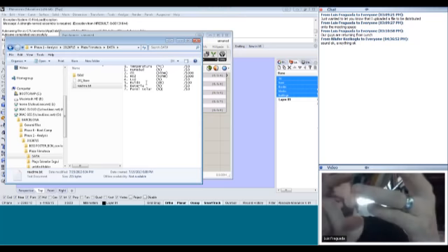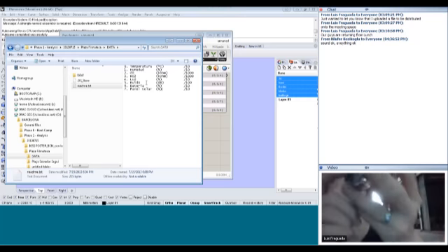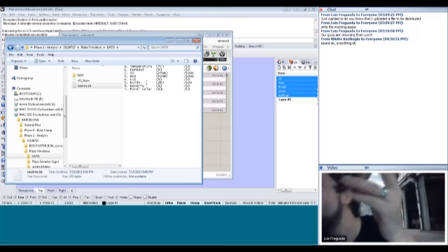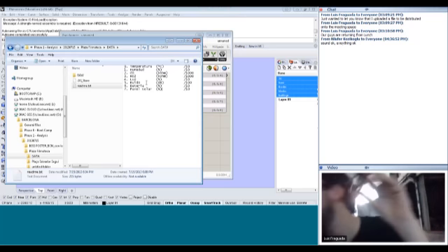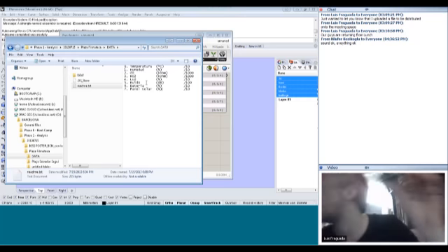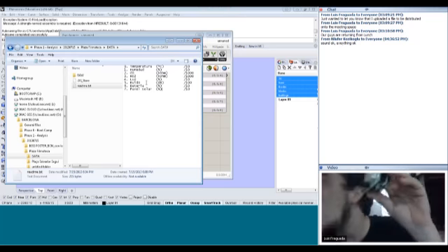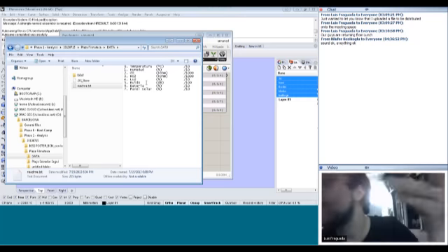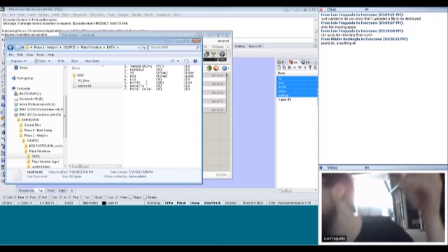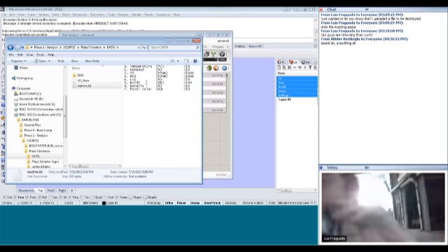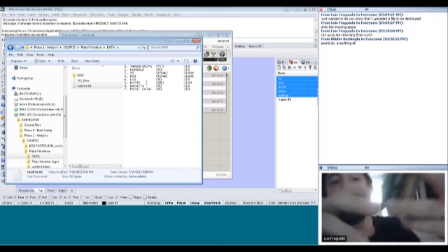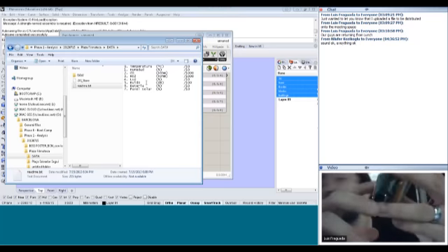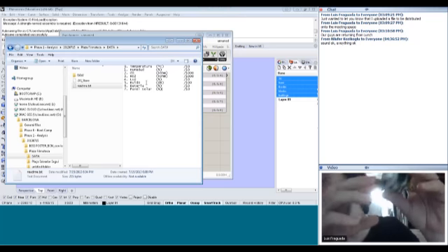So this temperature sensor has a specific behavior, that at a certain resistance equals a certain temperature. At a certain resistance, it equals a certain humidity. And that's the same for the rest of the sensors. The noise sensor as well: at a certain value of kiloohms, that translates into decibels. Some of the math is really straightforward, how to go from kiloohms to the value that we think, and some of the other math is much more complicated.